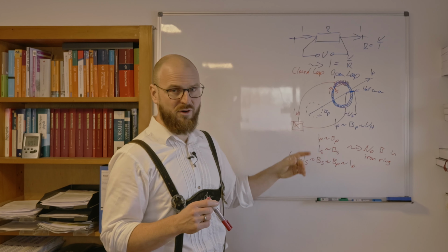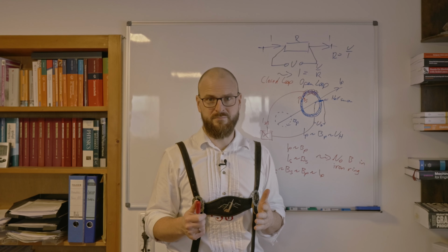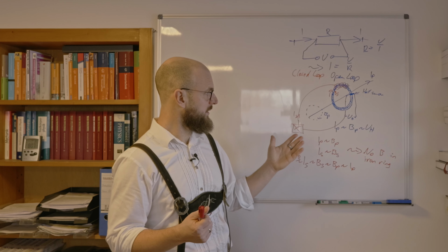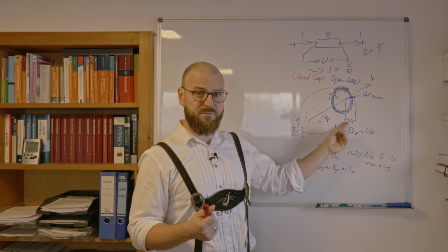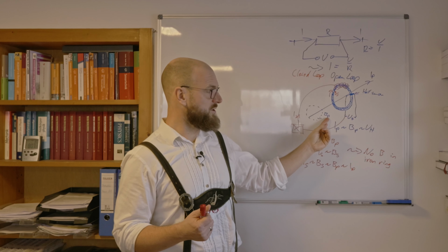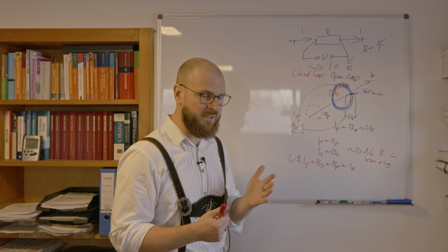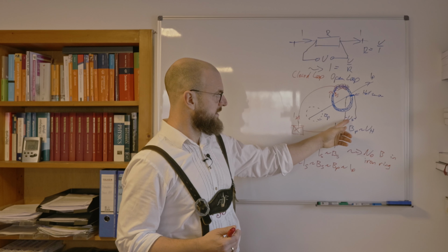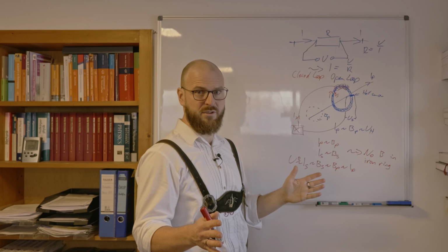Moreover, that control unit over here simply has to do nothing. Meaning, it's a proportional control unit. The Hall voltage measured over here is directly proportional to the primary magnetic field. So we just have to directly connect a current source controlled by that Hall voltage. Directly proportional.